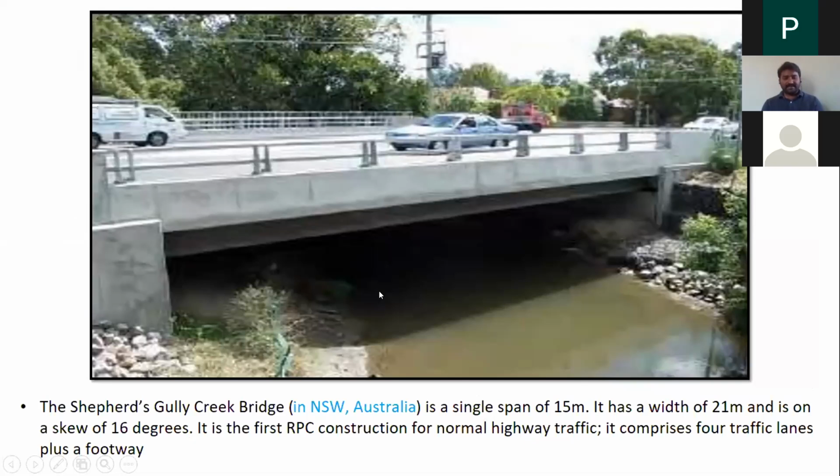Remember, as I said, this bridge is of reactive powder concrete. They have not used any reinforcement here. Only steel fibers they have used as reinforcement. Without reinforcement bars, they have constructed this vehicular bridge. That is the advantage. Because of this high tensile strength carrying capacity, we may avoid using reinforcement bars at all.